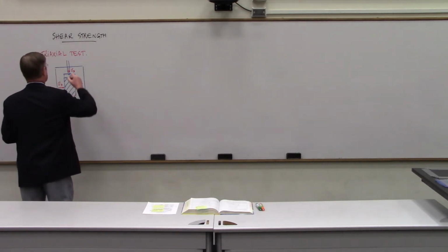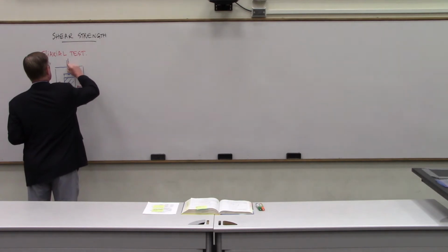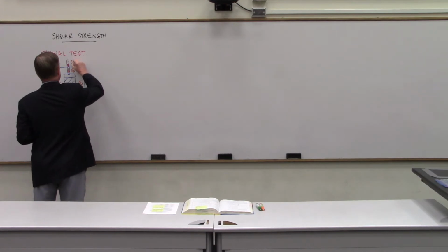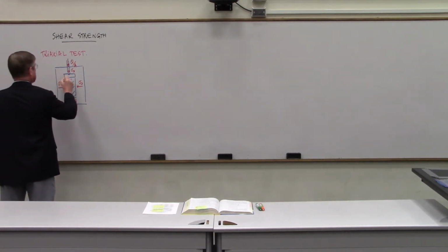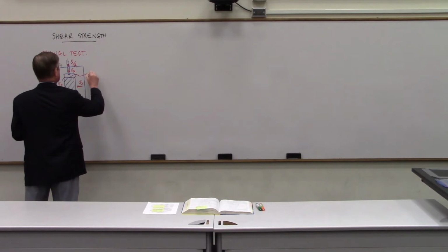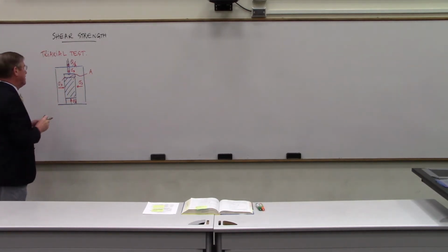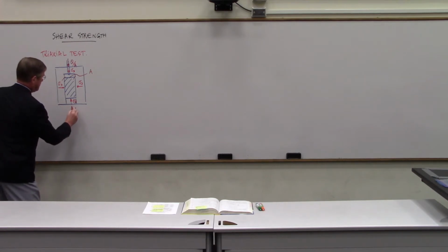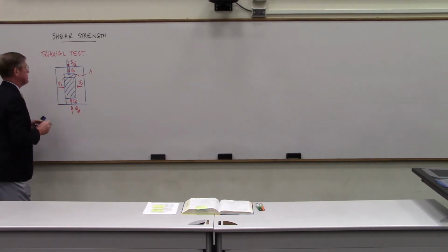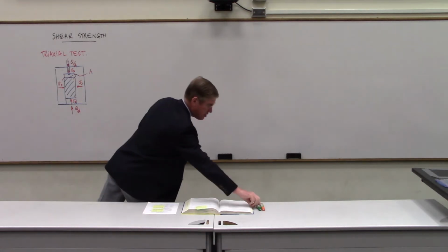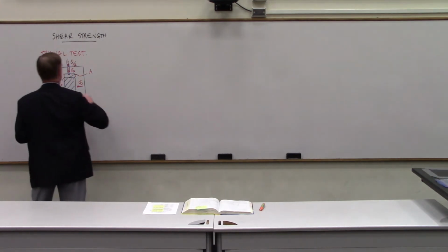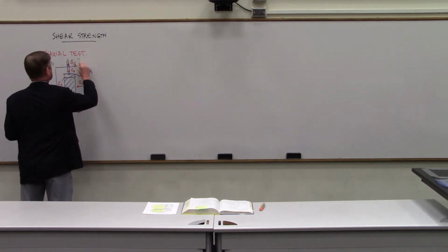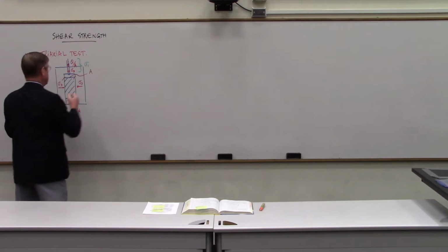And then we increase the load in the vertical direction, so we apply a load Q divided by this area A here. That's the cross-section area of the sample, and so Q over A is felt as well on this side, and the addition of Q over A and sigma 3 becomes sigma 1.